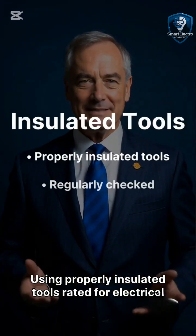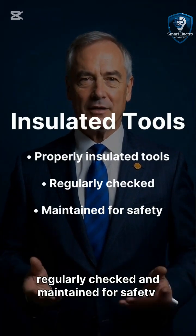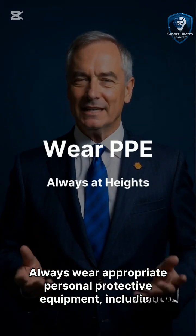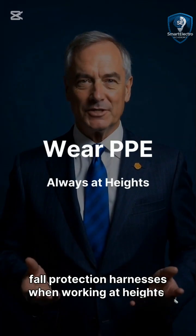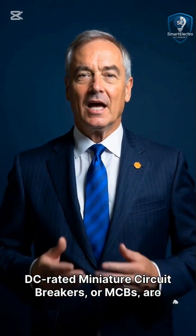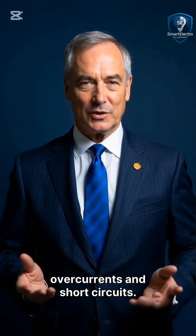Using properly insulated tools rated for electrical work is essential, and they should be regularly checked and maintained for safety. Always wear appropriate personal protective equipment, including insulated gloves, safety glasses, hard hats, and fall protection harnesses when working at heights. DC-rated miniature circuit breakers, or MCBs, are critical for protecting solar power systems from overcurrents and short circuits.